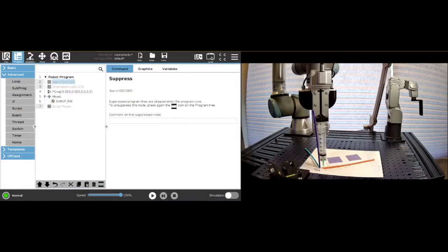All right, so now we're going to discuss all the details about moving using variable waypoints and all the different methods that we described earlier. The first one we want to do is move relative to the base. We're assuming here that we have a plane defined as it is here. This is our origin. It's called sketch rotation, and it has our x-axis along the orange line, the green line defines the y, and the blue defines our z.